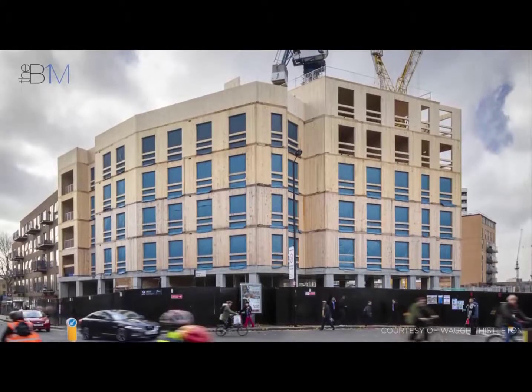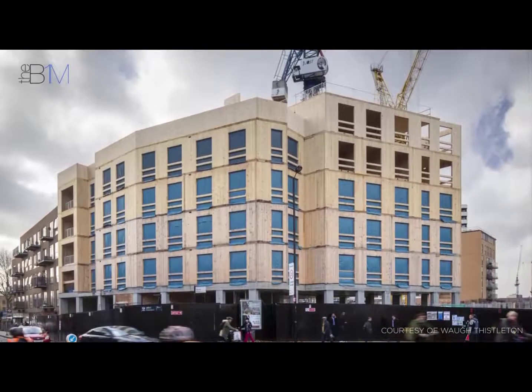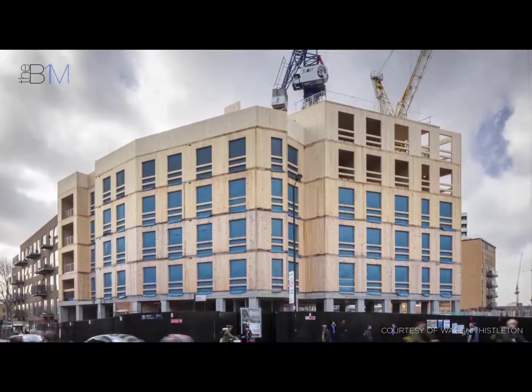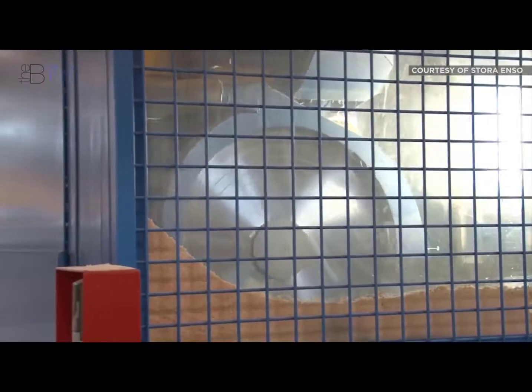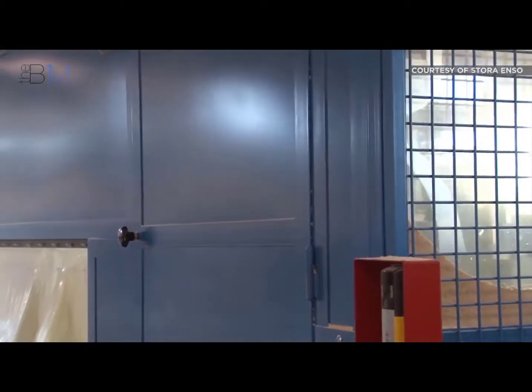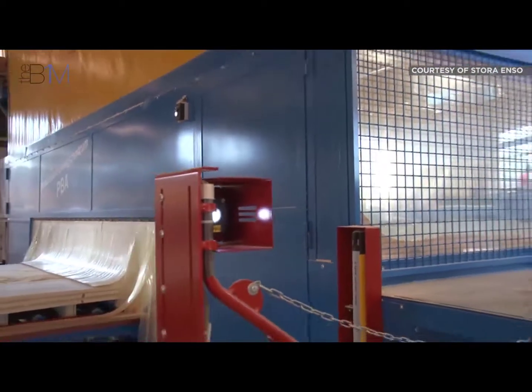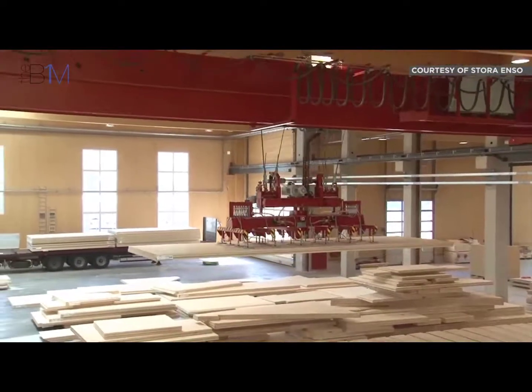Individual panels can in theory be any size. However, their width is limited by the size of the manufacturing machinery, which is usually around 11 feet or 3.5 meters wide. The length of the panel is only dictated by how it will be transported to site. While 45 feet or 13.5 meter lengths are typical for practical purposes, panels of up to 75 feet or 22 meters have been produced. Using state-of-the-art, computer numerically controlled or CNC joinery machines, almost any shape of panel can be produced, meaning that door and window openings can be pre-cut in the factory. These off-site manufactured panels are then ready to be delivered to site.